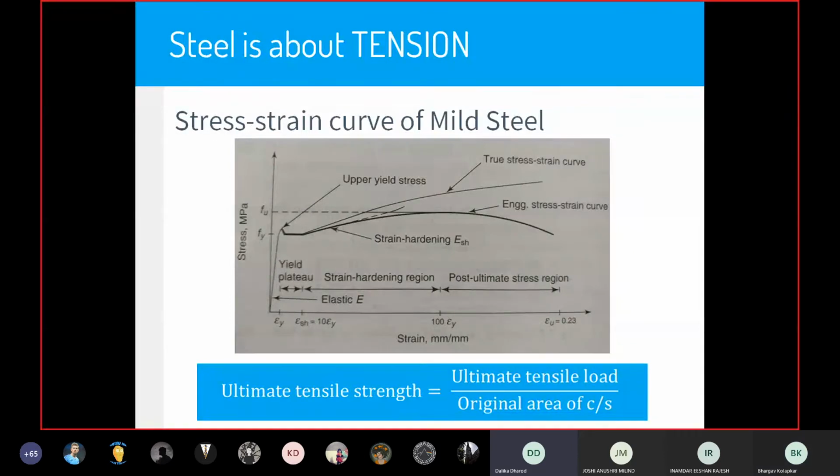So in that sense the engineering stress and strain would be the same as the true stress and strain, right? It won't change because the load is not changing. So why do we need two curves, because the load doesn't change? You calculate for a load that is going to be constant throughout.